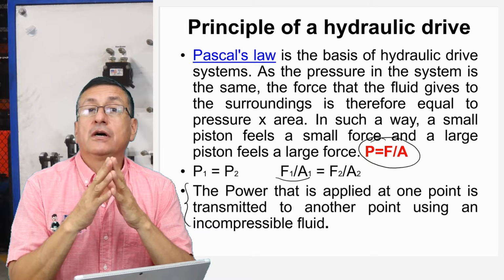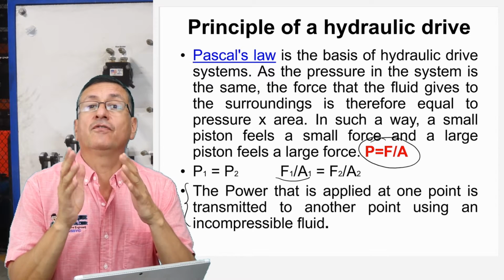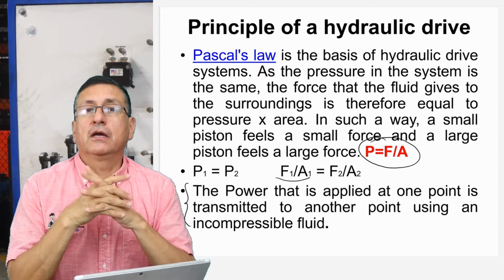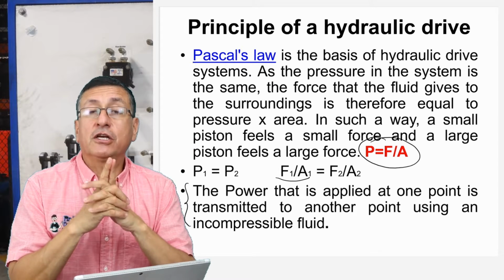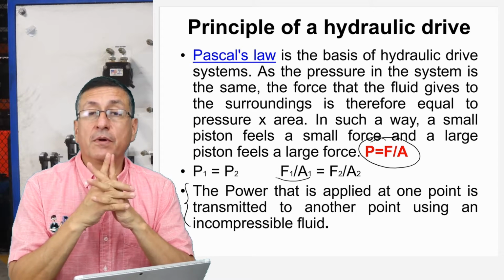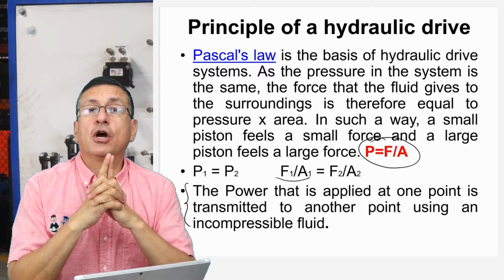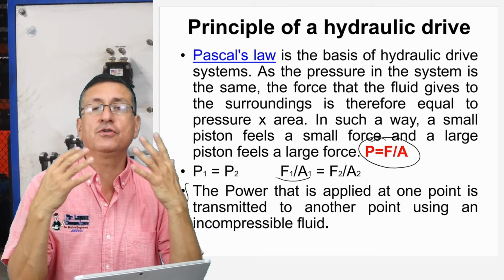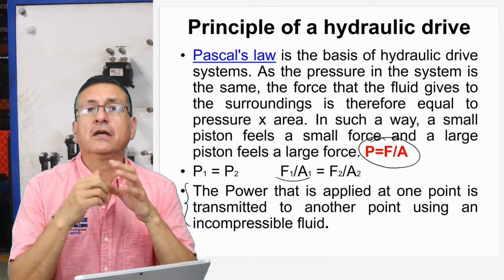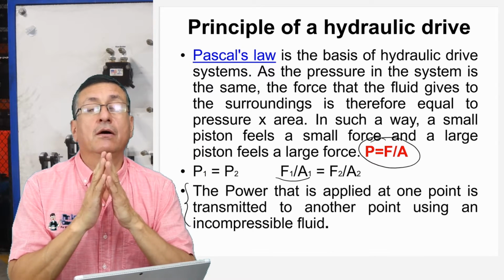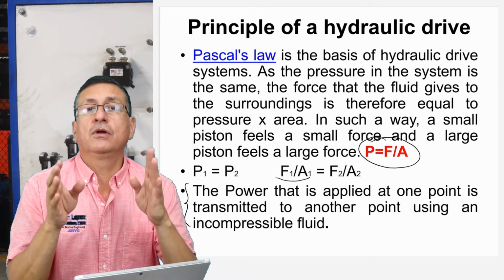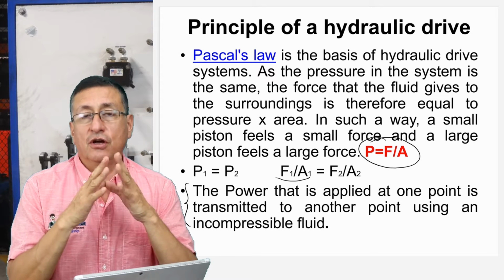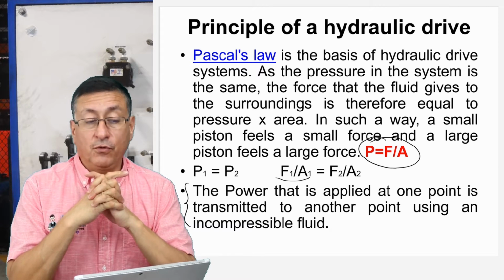Those additive fluids are different depending of the application. Yeah, the people know the most common hydraulic fluid is the automatic transmission fluid, the ATF. You remember that, the red one. This is the most common. I love that fluid, because I consider it universal. You can use that fluid in different types of hydraulic system. But once again, follow the manufacturer recommendation. Follow the instruction of the manufacturer according with the fluid.